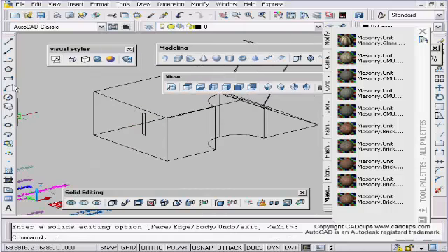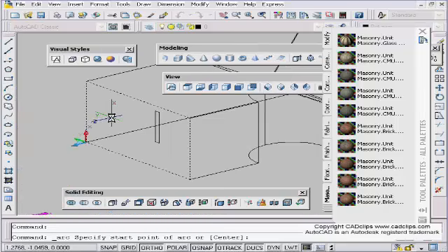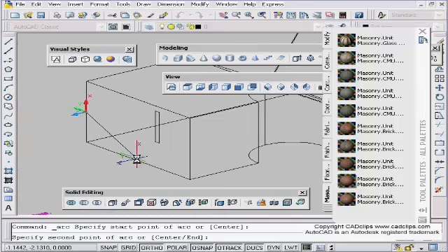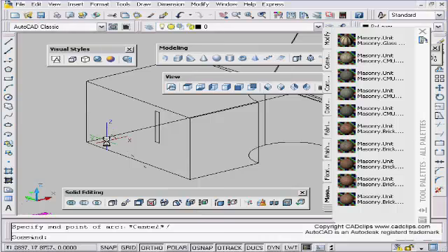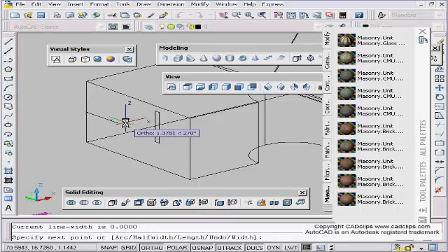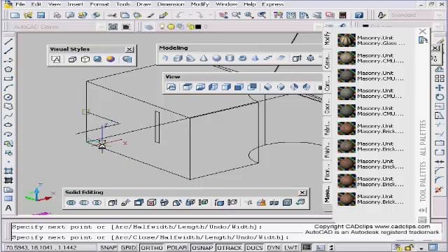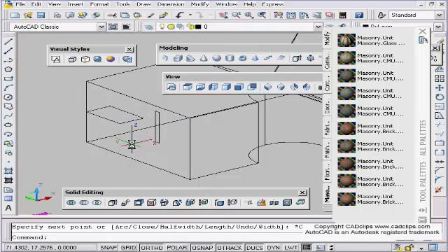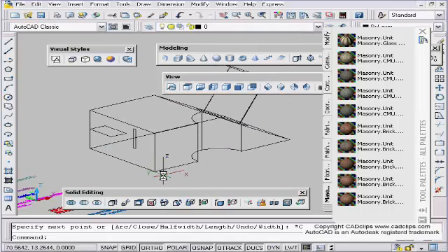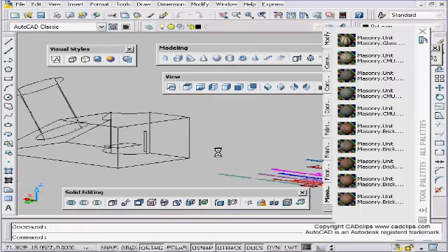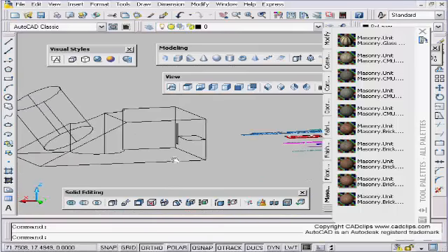Okay, so anytime you want to draw an object or an arc, you can pick a face. Wrong type of arc. Okay, maybe a polyline from here over, and around depending on what you want. Place a snap mode, click, click. Okay, start it on that face. Doesn't matter. Shift middle mouse button. You can see where that is.